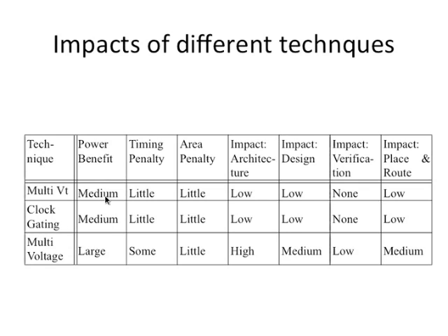Multi-VT is another technique where you can have standard cells with multiple different threshold voltages: high threshold and low leakage, and high speed and high leakage, and the design tool again basically takes care of which one to use when. Right, and again this is very transparent to the designer. You just say, okay, I need to meet this speed, and then the tool will have to figure out what is the right one and use that.